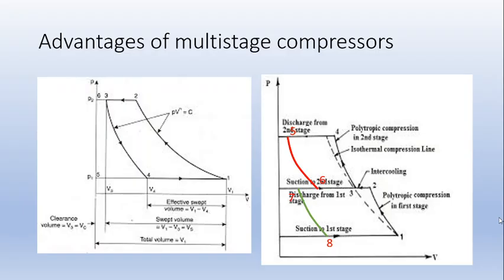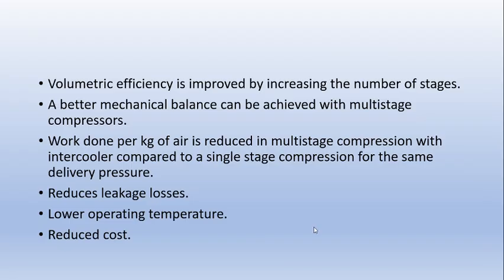Next is the advantage of multi-stage compressors over a single stage compressor. This is a single stage compressor, this is a multi-stage compressor. The main advantages are the volumetric efficiency is improved by increasing the number of stages. That is one of the main advantages of multi-stage compressors.